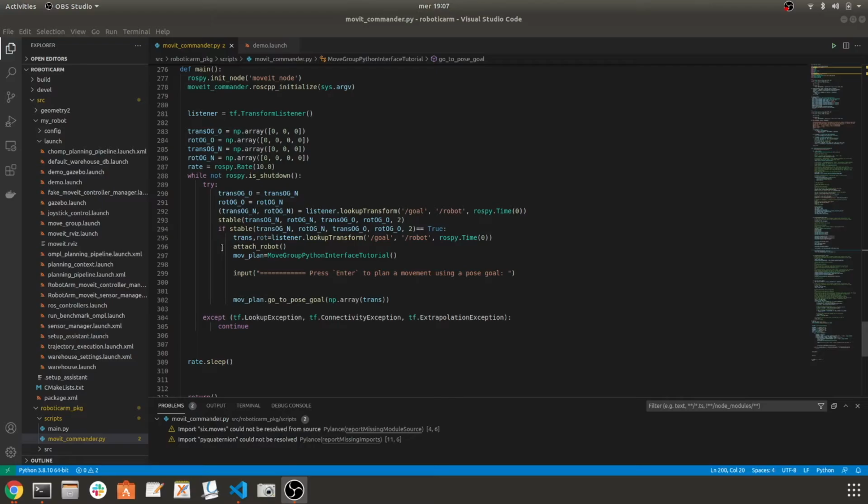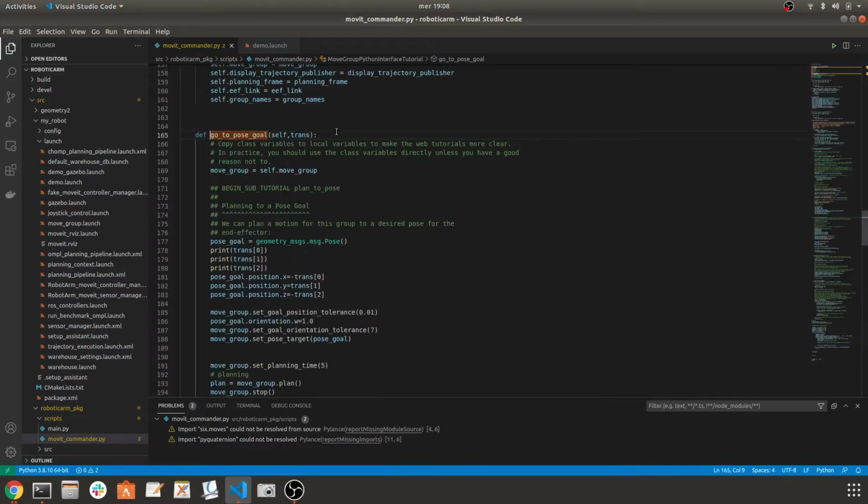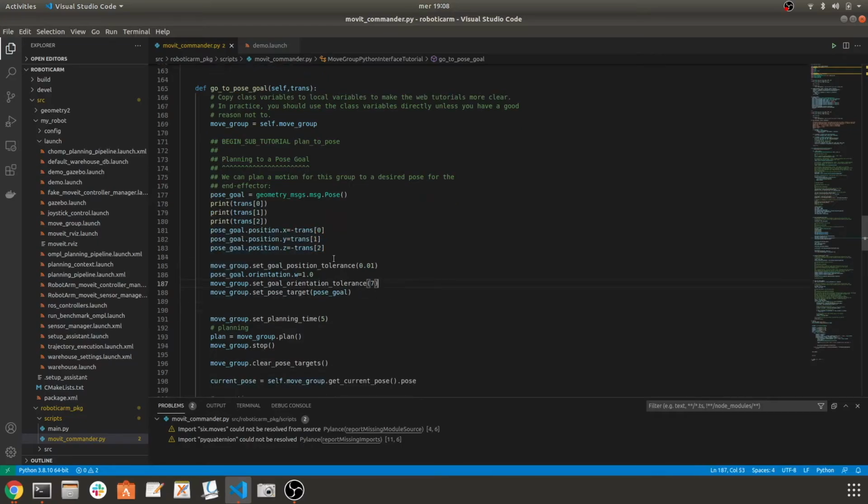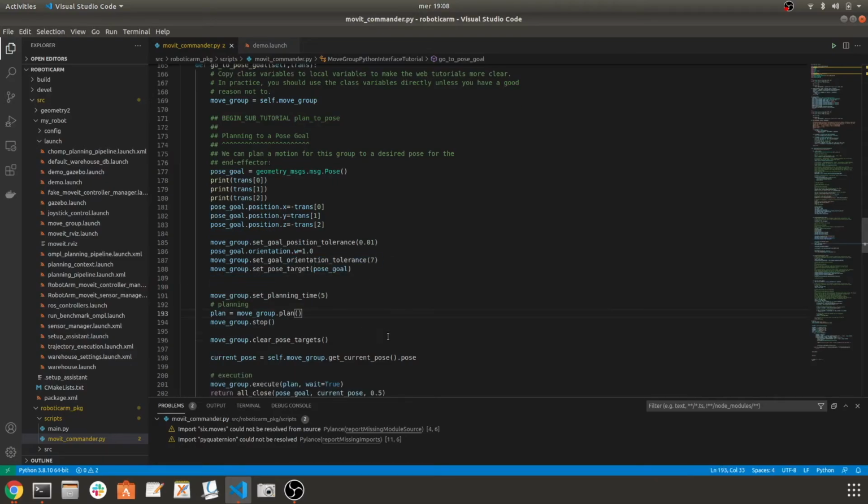Lastly, we can now see our implementation of MoveIt. We start by waiting for the translation between the robot frame and the goal to stabilize. We now use this transformation as an input for the function goToPose we implemented to perform the trajectory planning. We align the transformation from the robot frame to the goal's one with the base link, which is used by the kinematic solver to compute the trajectory planning. In order to avoid numerical problems, we set a 1 cm tolerance over the position of the end effector. Since our only interest is for the TCP to meet the goal's origin and not to have the respective frames coincide, we impose a rotation tolerance greater than 2π, otherwise almost no solution could ever be found.